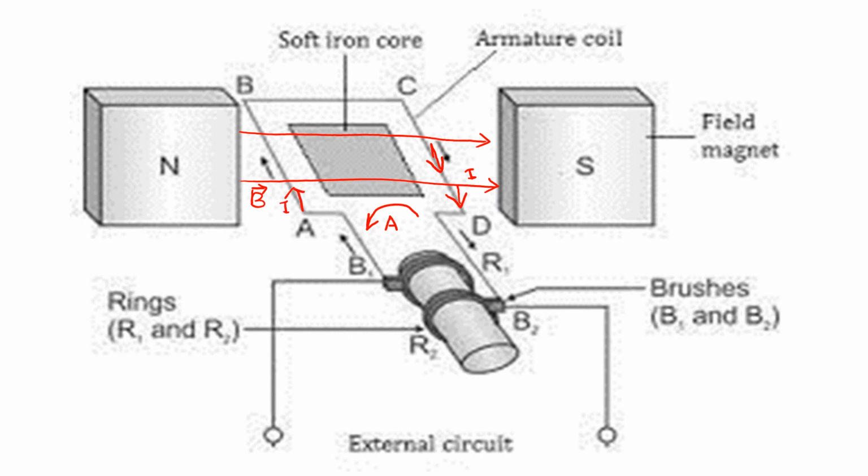Induced current is upward. So now, since you know that the current flows from the positive terminal toward the negative terminal of the source or of the battery, and now the current is flowing in this downward direction, then this ring and the brush attached with this ring will act as a positive terminal, because current is flowing through the positive terminal.